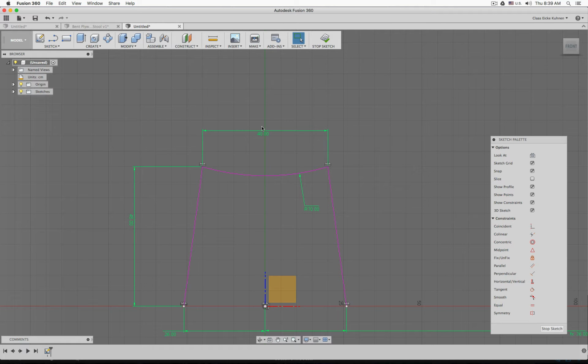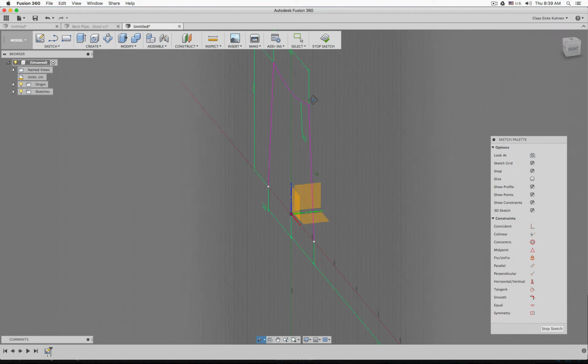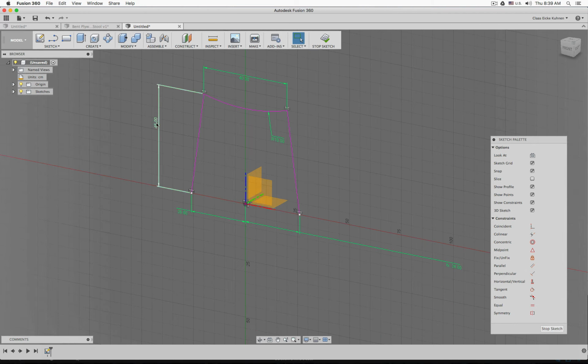So that's actually not ideal, which is why, if I don't have to, I will not fillet the sketch. I will keep the sketch very simplistic, very basic. So later I can easily, by double clicking these numbers and giving them different values, adjust my sketch. The same methodology I apply in Blender, to work with very basic geometry, I do here as well. No matter what CAD environment you work in, that's a very good piece of advice. The most basic steps to get your work done.